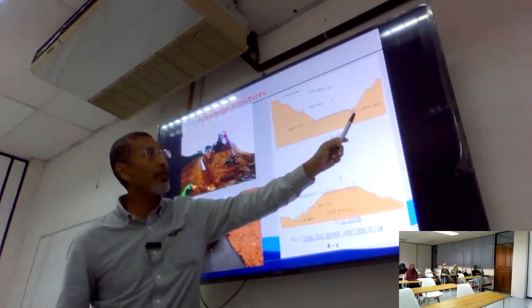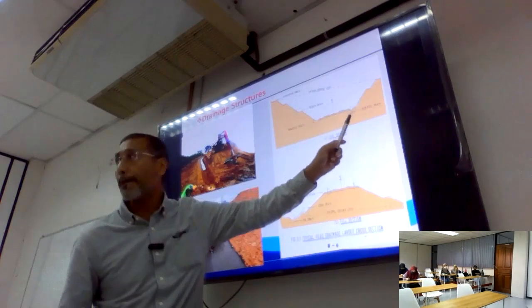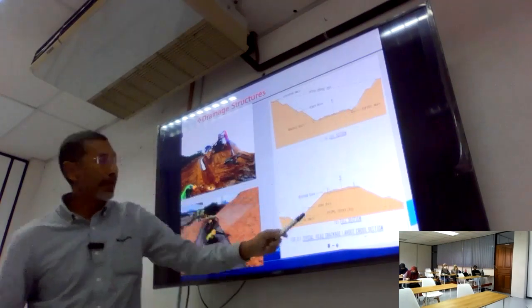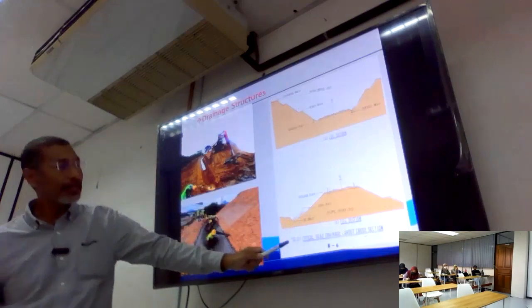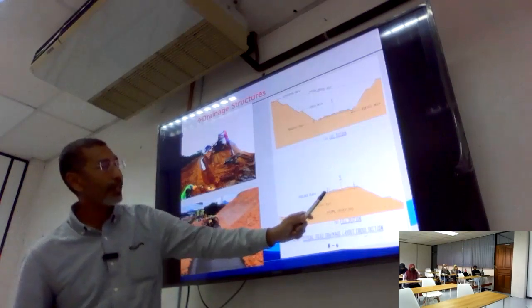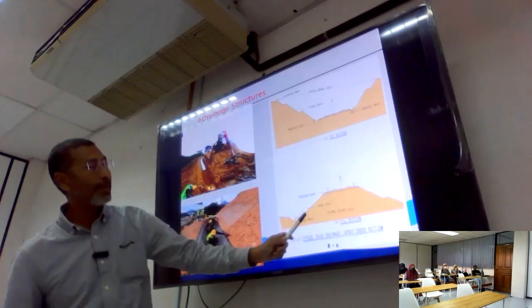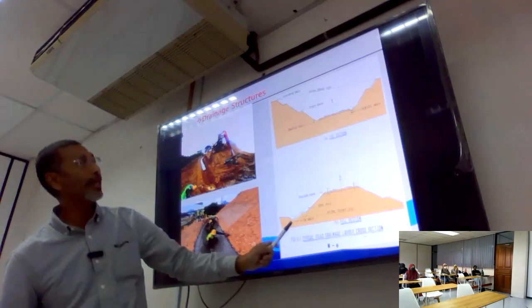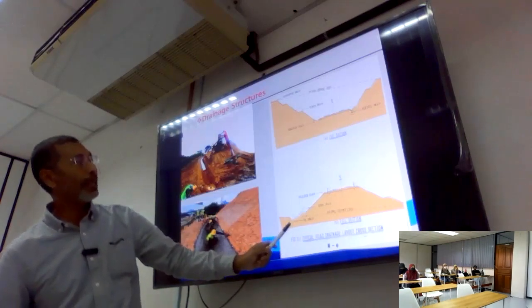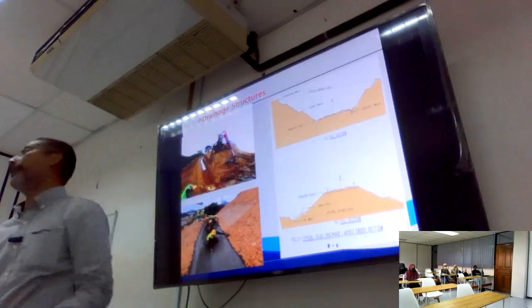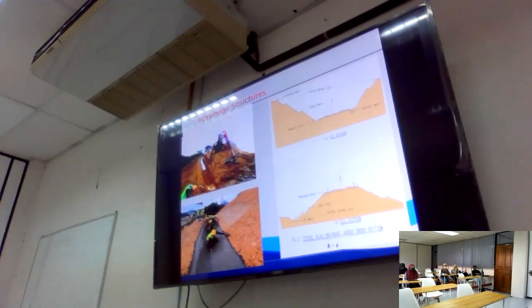Of course, in some areas you need to provide a subsoil drain below the drain. If it is an embankment like this, up here you have a shoulder drain. In between you have a berm drain, and of course at the end you have a toe drain. Right? So the toe drain is the opposite of the interceptor drain. Right? So this is a construction of what drain?